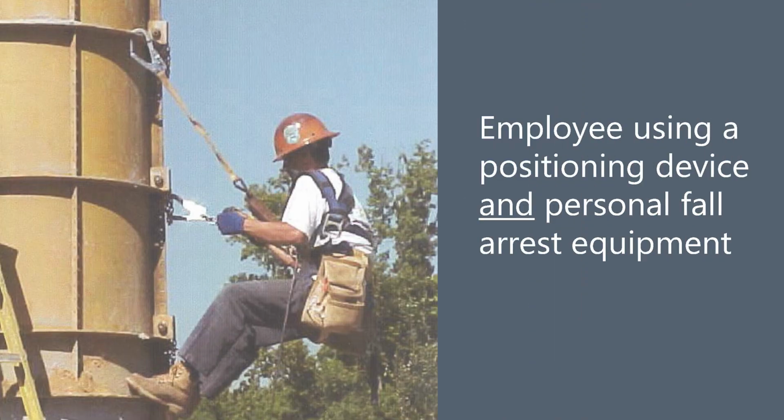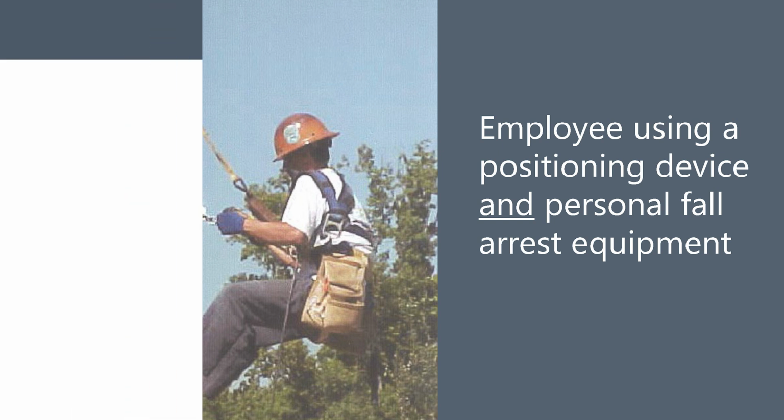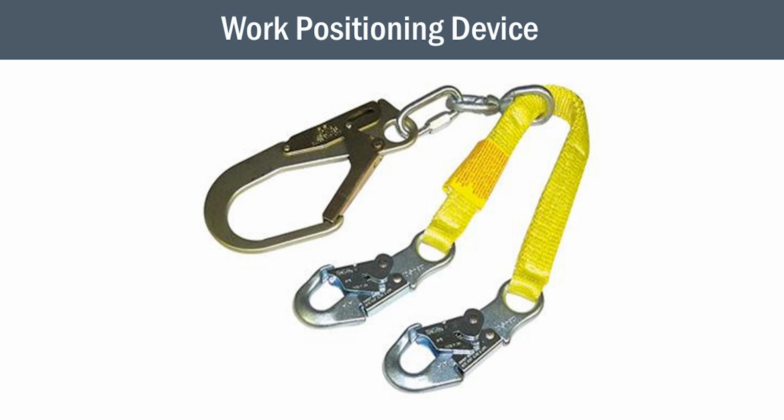Here's a good picture here showing a work positioning system. It's built in with their fall arrest system. How far can that person fall? Not far at all. Okay? And this would be more of a device you may see used in this system.